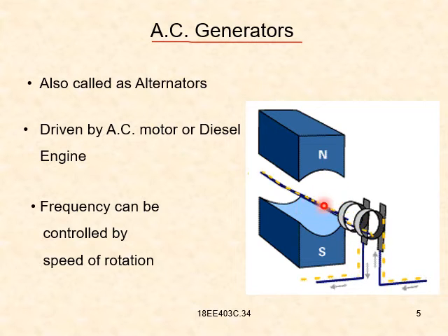That is why you can see the EMF is induced. These two are the slip rings, where we can collect the supply from the rotating elements. Since it is rotating, we cannot directly take the supply, otherwise the wire gets wound. That's why there are two slip rings for phase and neutral, or plus and minus.